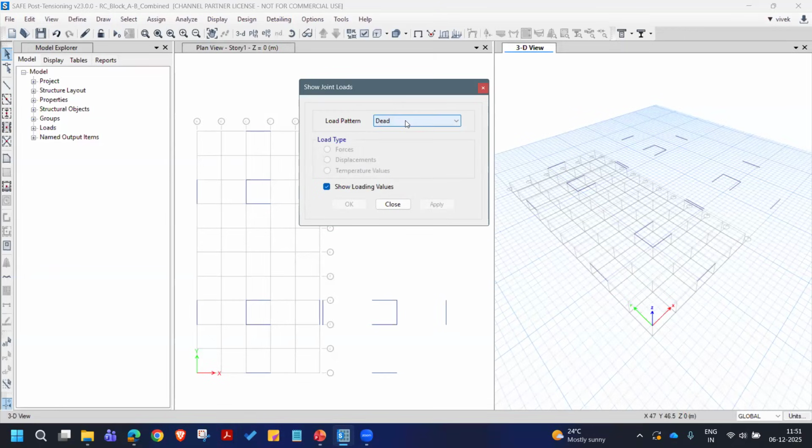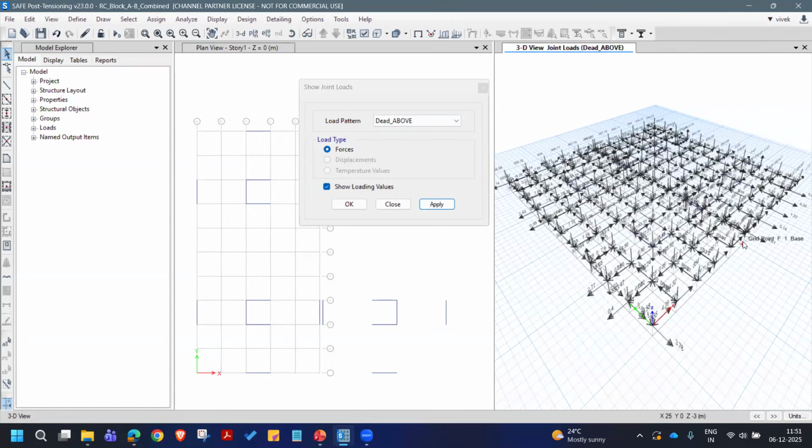But generally, in addition to the existing loads from above, we can also add some uplift pressures, sustained soil on the footing, or other live loads acting on the base mat, which can be applied directly on the objects. For that, you can directly use one of these patterns. Above will be the imported loads, right? So generally, you don't have to worry about this segregation; the program handles this completely for you. So what we are trying to show here is the loads imported. Can you see?